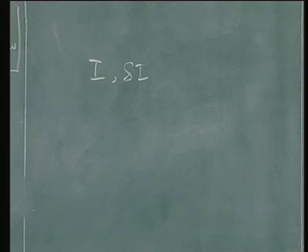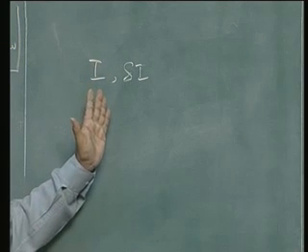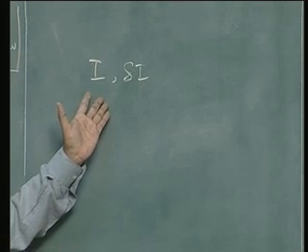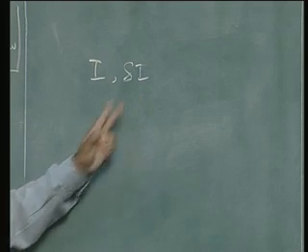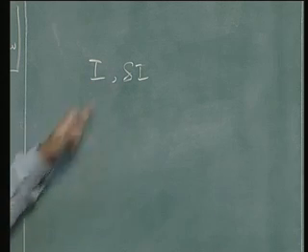So you can go either to virtual work or to the variational form. We also commented that many times a variational form may not be available, so you stop with the virtual work principle, because you need a constitutive equation if you have to go to the next step.